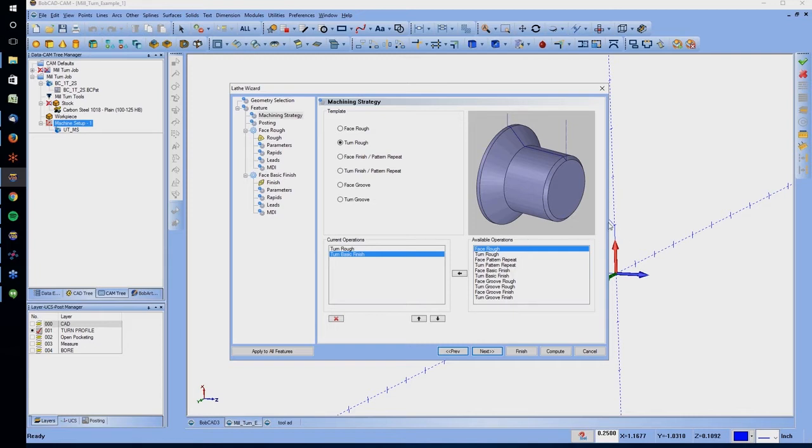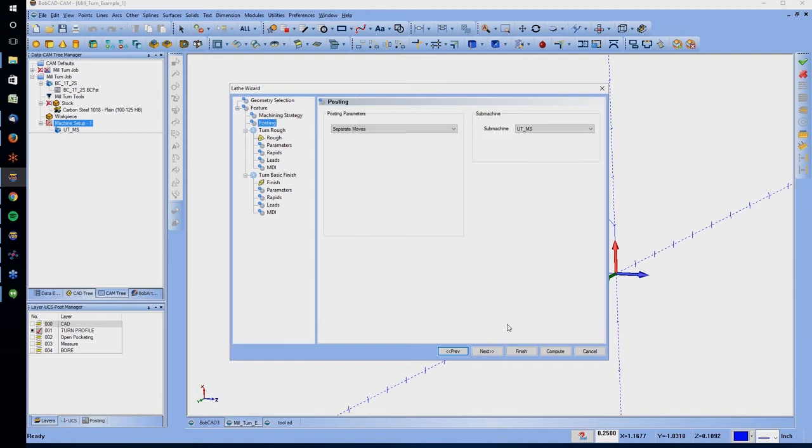Now, what we're going to do is, after this, we're going to go ahead ourselves, now that we have all this stuff defined, and we're going to define the next setting and move on to the next phase. So on the next phase, we're going to say Next, and you're going to have the option for the actual turning option to choose separate moves or can cycles. Or you guys can long code it out, just depends on how you guys want to output those particular settings.